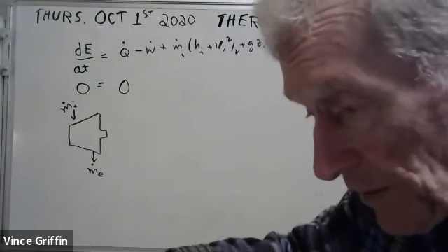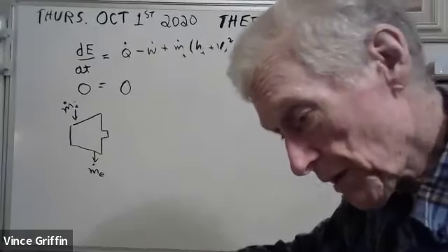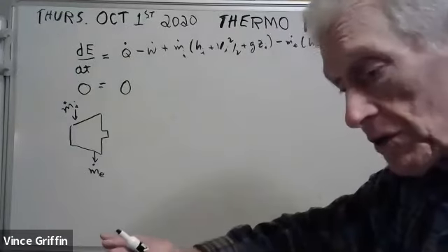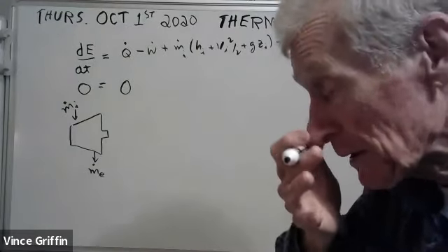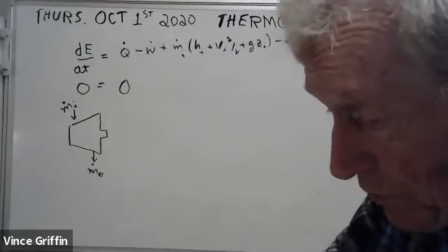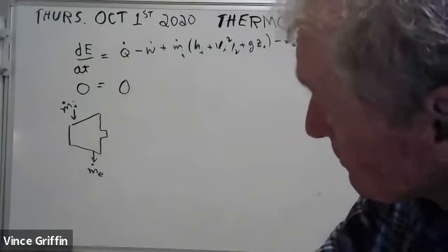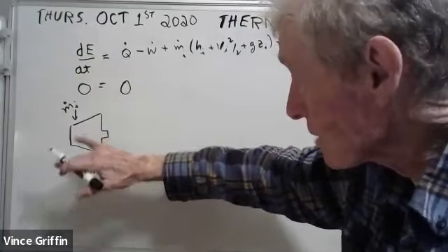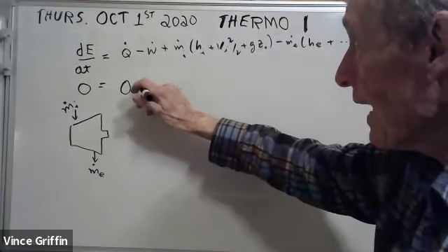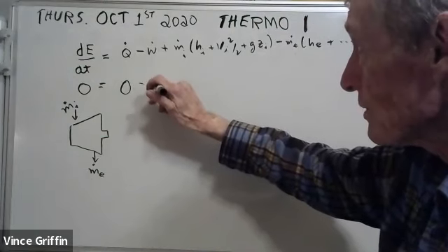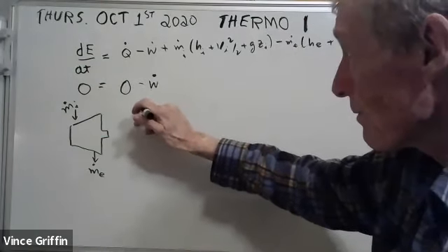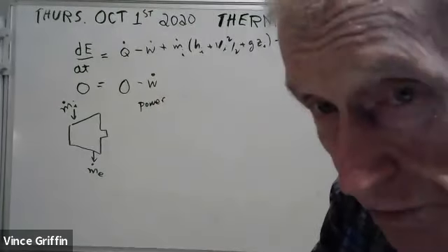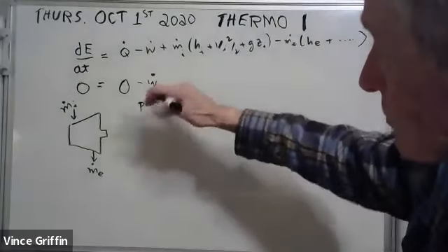You see, when you fire it up and you're starting up the turbine, that's not steady state. But once the thing achieves all of the pressures and temperatures you want, and the mass flow rates that you want, that they're all constant, the energy doesn't change with time inside your turbine. But this time we don't put a zero on this one. This is the power. And that's the reason why you have the turbine. Turbines provide power. So we don't get to cross that out anymore.